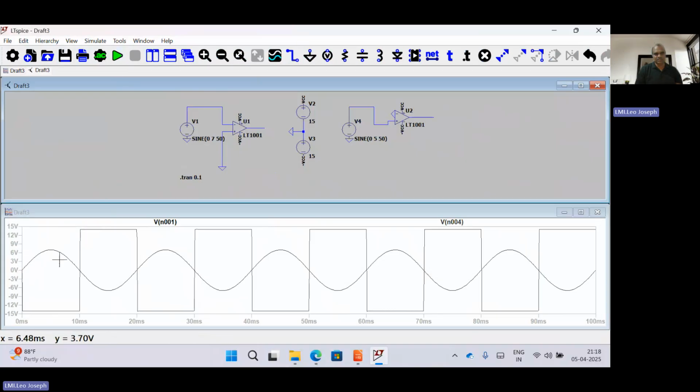You can see here, this is 0. This is going to the peak voltage and it is crossing here. The crossing point is 0. Once again it is crossing the 0 point. So at that period, what is the level of voltage here? +5 volt. When it is +5 volt, actually this and this 0 reference point are compared with each other. That is, 0 is lesser and this point is greater. At that time, you will get a -V saturation, since the mode of operation is inverting amplifier.